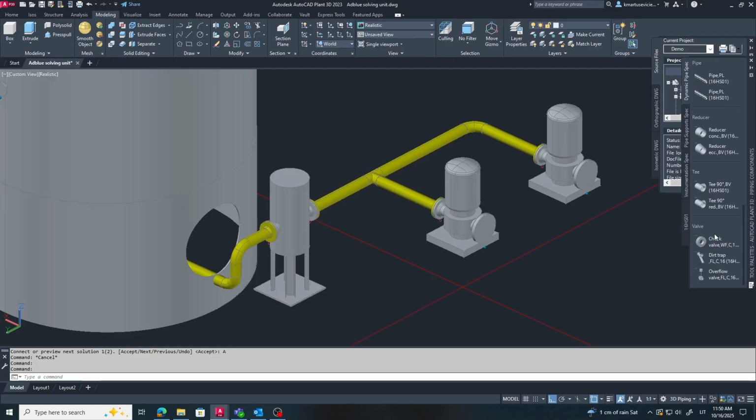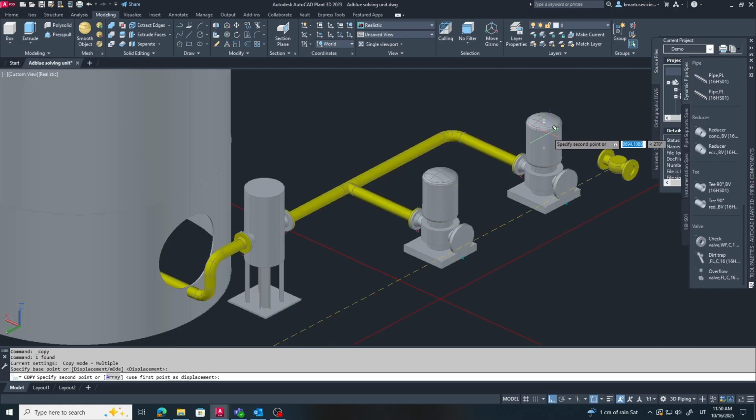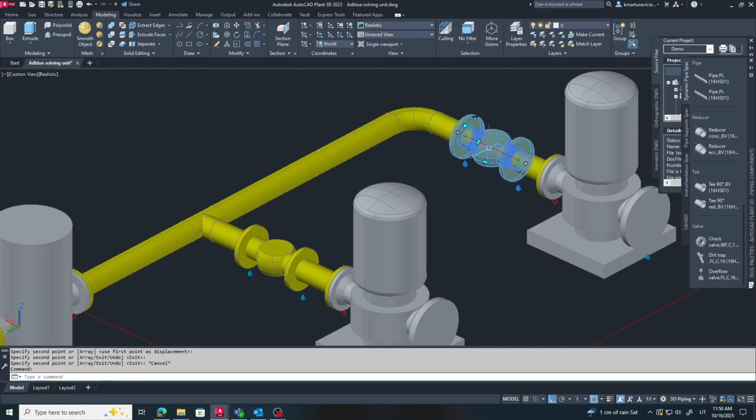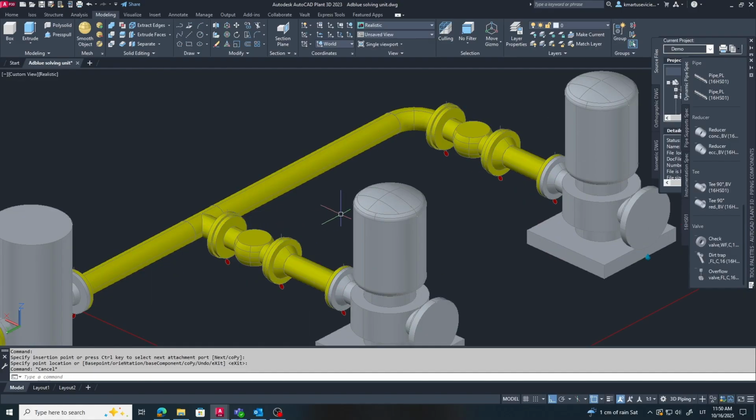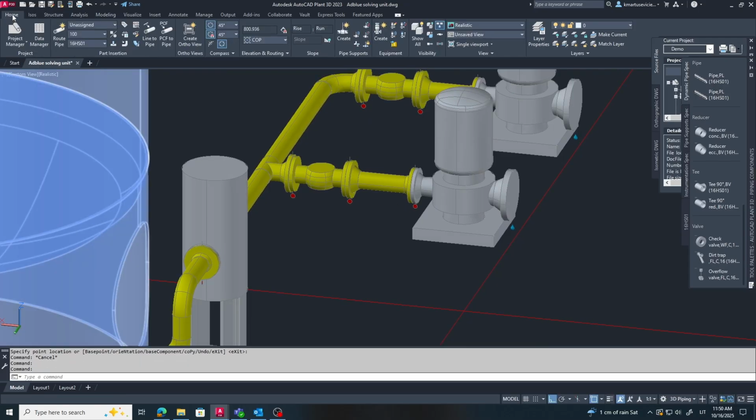As you see, I connected 2 pumps and a filter to the reactor. The principle here is very common in real factories. We have 2 identical pumps. One is working and one is in reserve, so if the main pump fails, we can switch over instantly without stopping production. These pumps take the solution from the reactor and send it through the basket filter.